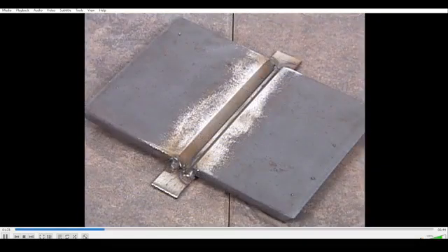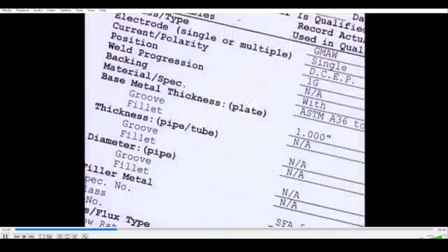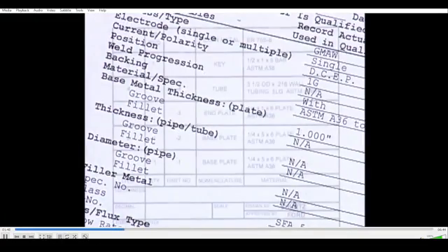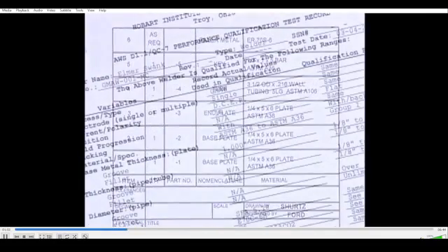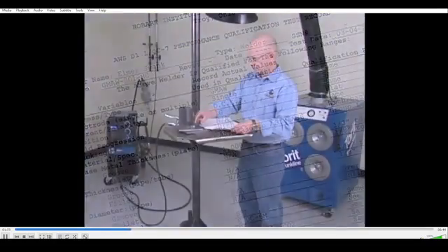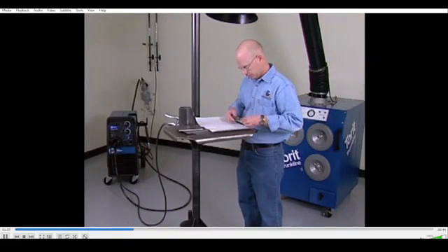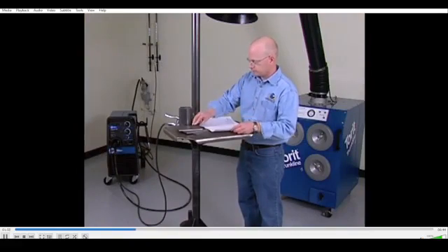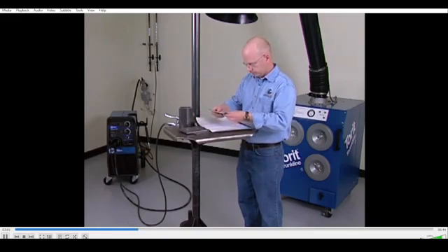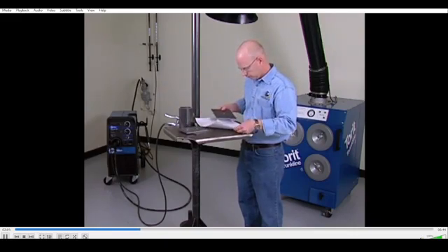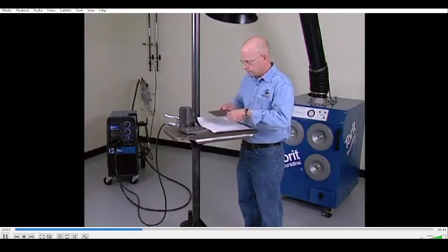The first area of visual inspection takes place before welding and is likely the most important. Proper inspection prior to welding can eliminate errors which lead to costly defects in the weld or weldments. The inspector should become familiar with all aspects of the job, such as material specifications, the bill of materials, and the welding procedure. When completely familiar with all the written details, the dimensions are compared to the engineering drawings to verify that all parts are within tolerances. Improperly dimensioned subassemblies lead to difficulties in the final fit-up of the weldment.